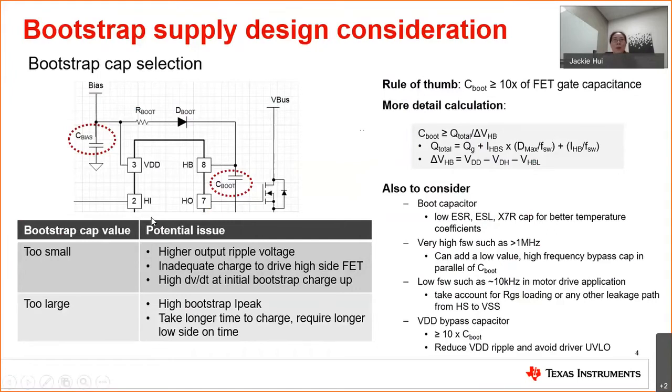The value of the boot cap cannot be too large either, because a larger cap takes longer time to charge. What that means is the application needs to keep a longer time for the low side to be on. It may not be applicable to some applications.